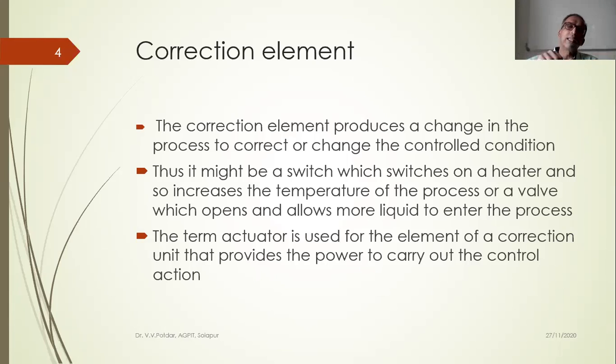It will send the signal as a feedback signal to the comparison element. The comparison element compares the actual temperature value with the set value. Now, what is the set value? Let us say I have set the value to 1600 degrees Celsius, which is the temperature I want inside the furnace. So for 1600 degrees Celsius, the reference input element will convert that into an equivalent of 16 volts.